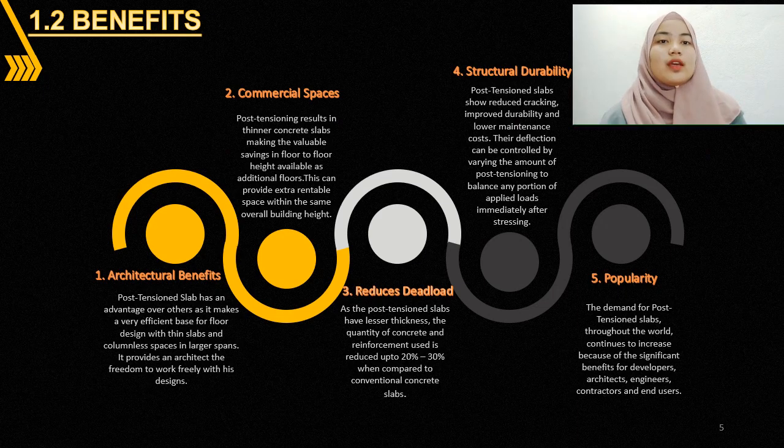Five benefits of post-tension concrete. Number 1 is architectural benefit. A post-tension slab has an advantage over others as it makes a very efficient base for floor design with a thin slab and column-less space in a large span. It provides the architect the freedom to work freely with the design.